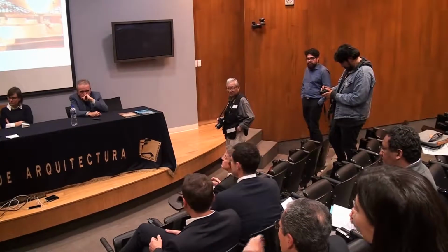Yes, I think he was obviously aware of Gaudí's work, but there are photographs of Gaudí's hanging models with cloth on them, but the cloth is not part of the form finding. The Gaudí models are only with rings, so they are not three-dimensional surfaces directly, and that's the difference between the Gaudí models and the Heinz Isler models. I think that with Heinz Isler they are actually the full surface structure. And obviously the final ones are made with latex rubber, which is a full surface.